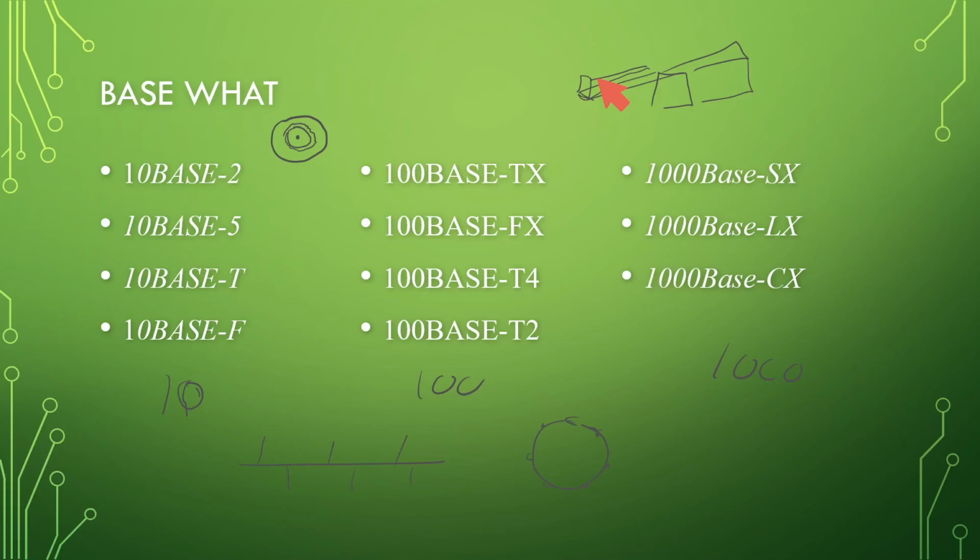You don't technically have to run fiber optic there. We just normally run fiber optic over long distances. If you're doing really short runs, under like 10 feet or something, you can just do copper over those super high speed network topologies. Just something to think about.